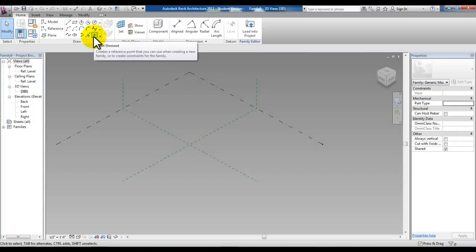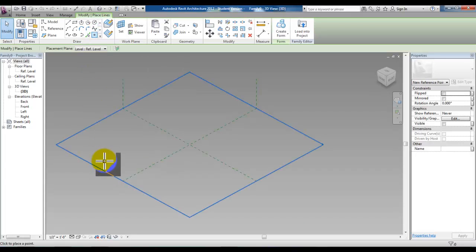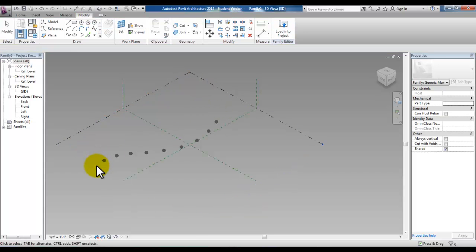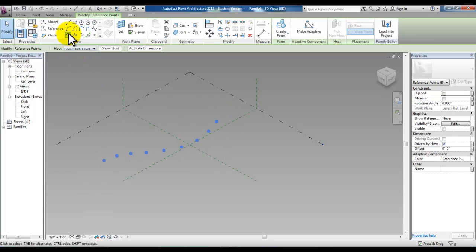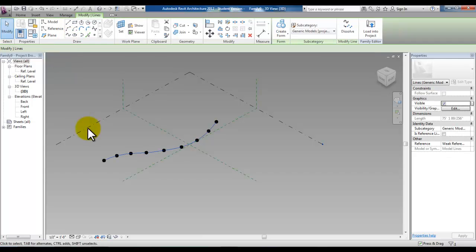these point elements, and we're going to pick points to establish kind of a spline and make the points kind of equally apart and not that far out of a curve. So what do I have? 1, 2, 3, 4, 5, 6, 7, 8, 9. We can select all of these points and pick the spline through points to create a spline through those points.